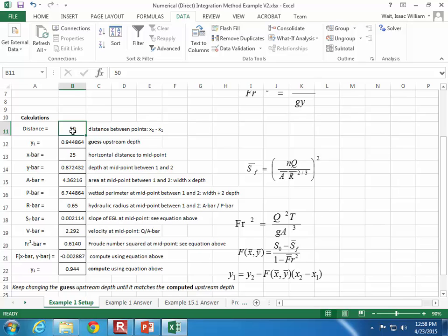So if we did it in 2 steps, then each of these little segments are smaller. And so we'd want to know how far apart is it to go from 0.8 to 0.9, and then how far is it to go from 0.9 to 1. And so you're breaking it up into smaller pieces, and you get improved accuracy. And actually in the homework, they ask you to do it in 3 segments, and I've given you the depths to use in between. That's the numerical integration method.